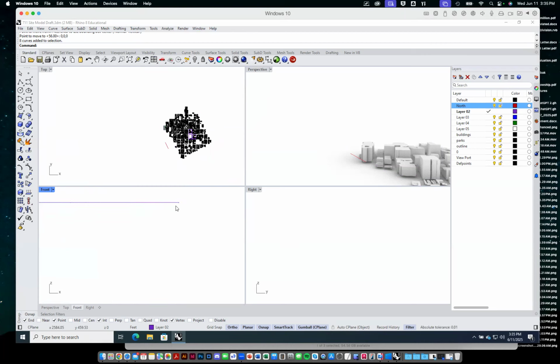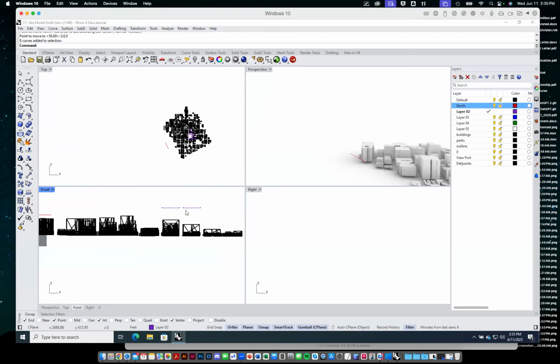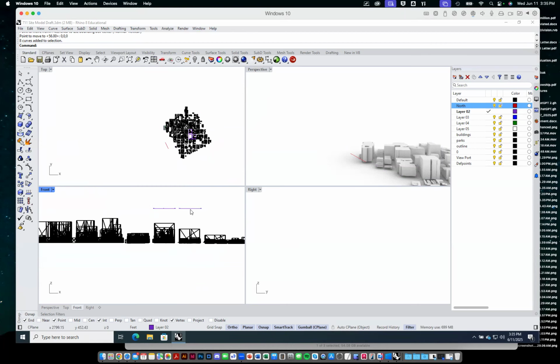You can see that I was drawing. I'm not sure if it's saying that some things aren't quite planar anyway, but everything's sort of resting on a plane way up here, right? That I was drawing. So I could sit there and try to move it around. I'm not going to bother trying to eyeball that stuff, right? What I'm going to do is make a surface at that zero XY plane, at z equals 0. And I'm just going to project those things in Z right onto that plane. Create a new set of planar curves. I can delete the old one, delete that surface, and then we have that stuff nice and planar, right?